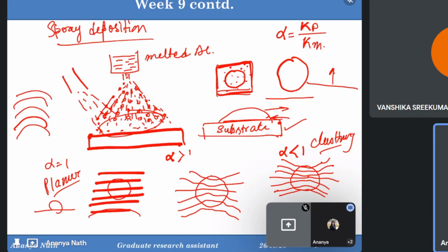It's not like it will not get melted. It will get melted. Welding, additive manufacturing, casting, wrought, everything takes place with the 5000 series and 4000 series. Researchers are doing a lot of work. But the main problem is you have to go for some other way of strengthening. You can go for cold working, where you introduce a lot of dislocations, which leads to strengthening. Severe plastic deformation gives low stacking fault energy, which again leads to strengthening. These are the well-known strengthening processes for non-heat-treatable alloys.